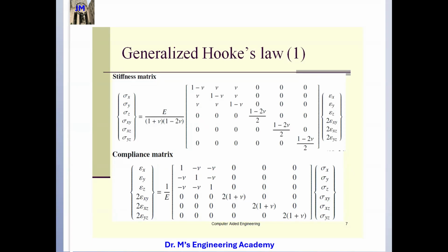However, if the stress components are known and you want to calculate the strain components, you are supposed to use this equation. Some students say, I'm good at mathematics. That's still okay. You can use this one, but you need to do the inverse by yourself.